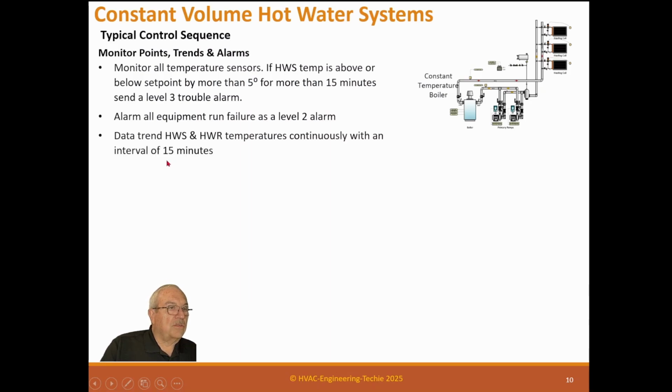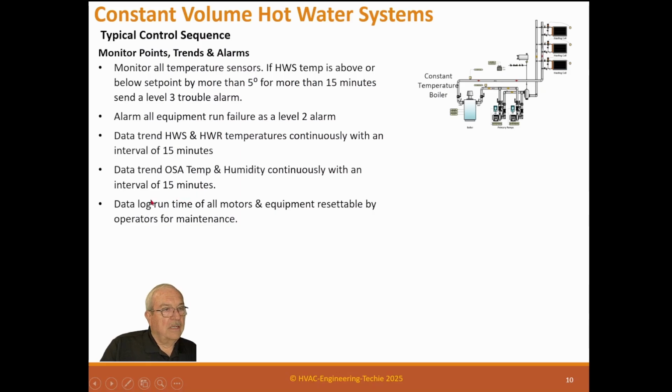Data trend hot water supply and hot water return temperature continuously with an interval of 15 minutes. Data trend the outside air temperature and humidity with an interval of 15 minutes. Data log runtime of all motors and equipment, resettable by operators for maintenance.